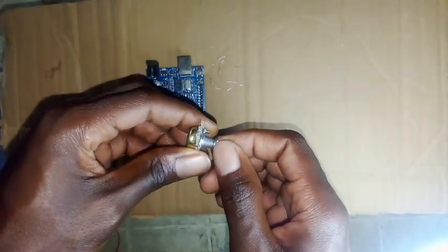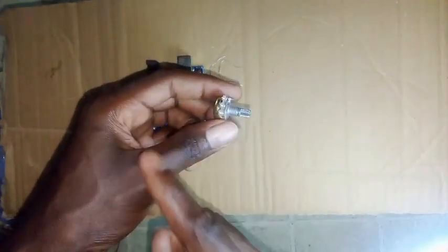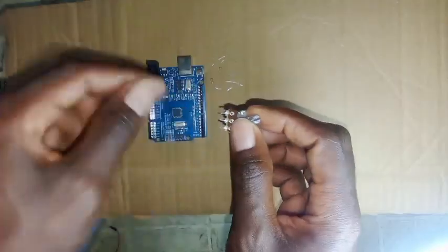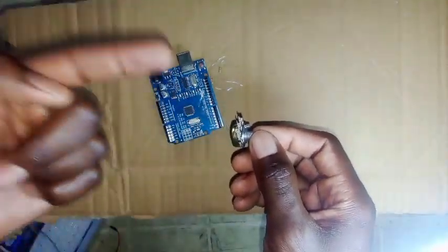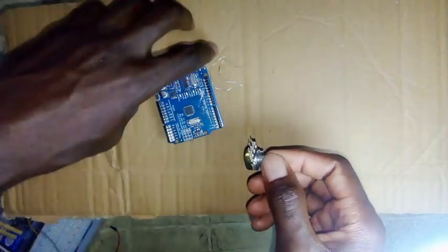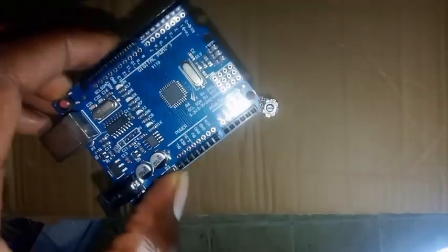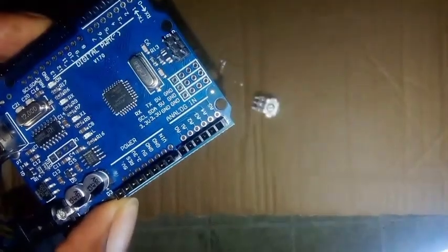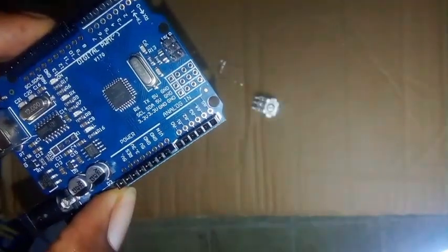Voltage is read from this, and this thing is continuous in time. It keeps giving values continuously. So that's analog, since the reading is continuous. That means we have to connect this one to the analog pins of the Arduino. Look at it, we can connect it to any of these. We can start from 0, A0. So we'll connect this guy there. So these are the guys we need.